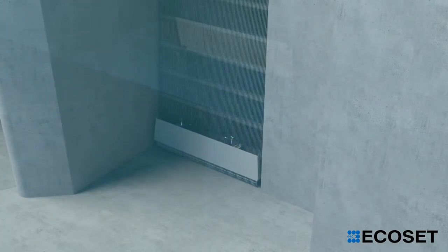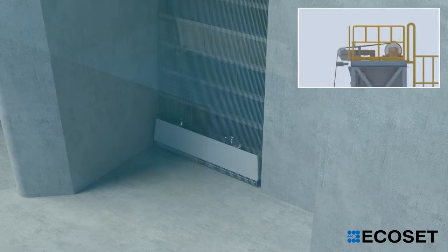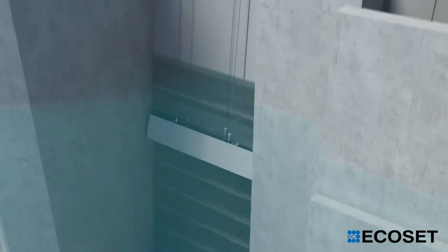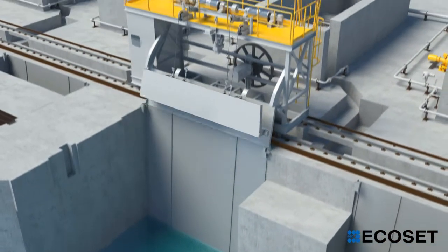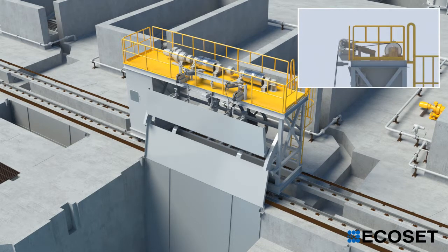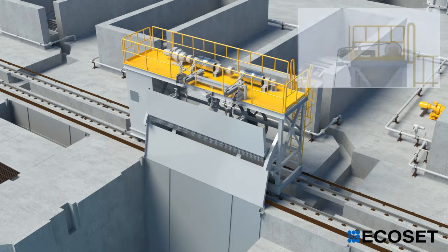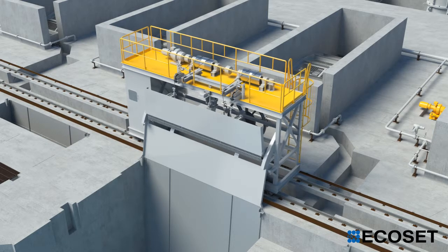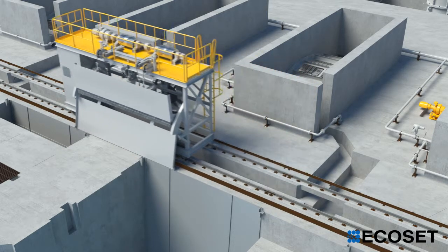Second, when the rake reaches the lower position near the channel bottom, it is stopped by position sensor and the teeth are rotated to their closed position. Third, the rake is lifted up the upstream face of the bar screen, collecting accumulated debris. Finally, as the rake reaches the discharge position above the operating deck floor, the teeth are opened and at the same time, the debris is discharged into a concrete trough. When all the cycle operation is finished, the rake is moved to another channel and the cycle operations are repeated.